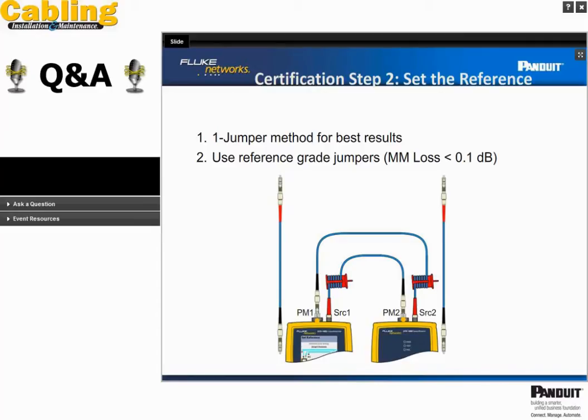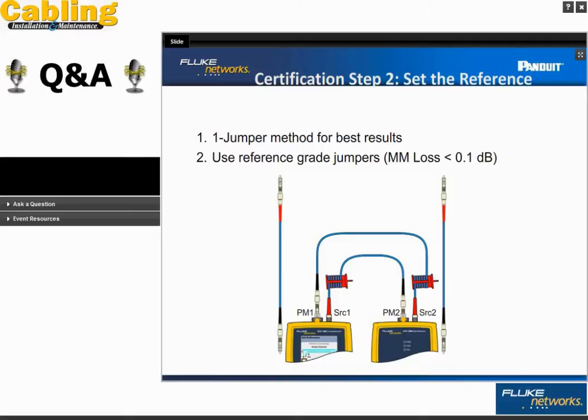The second question about bend-insensitive multi-mode fiber is an interesting one. A mandrel is basically a macro bend that strips those higher order modes away. If you use a bend-insensitive multi-mode fiber, it won't strip those higher order modes away at the rate that was calculated when the diameter of the mandrel was decided on.